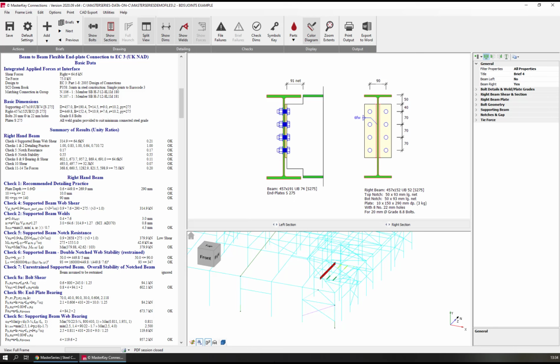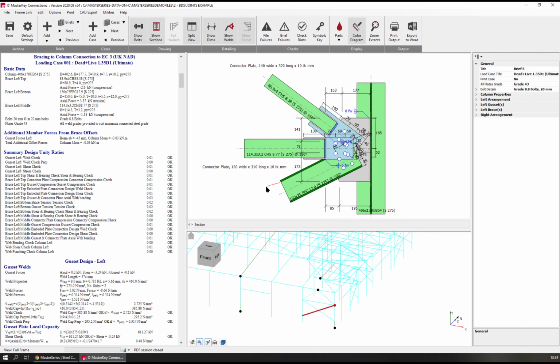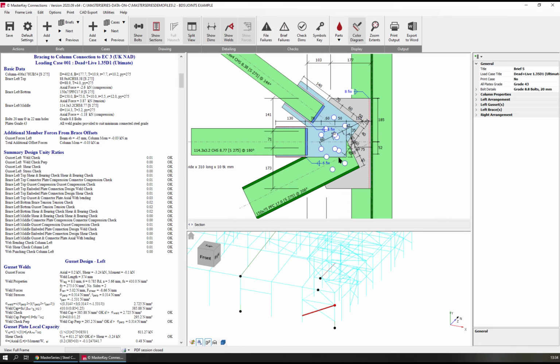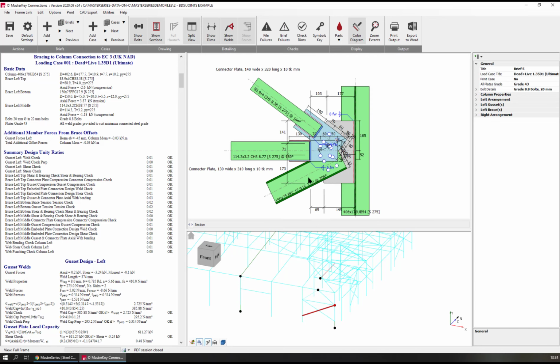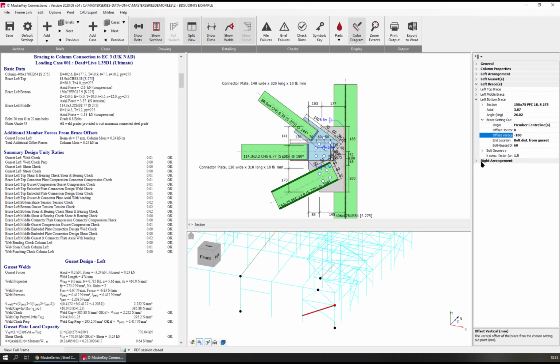Now we've got some more interesting items. We've got a bracing connection, which is coming in with PFCs and circular hollow sections. So obviously that's clashing at the minute and there's a bit of a log jam. So maybe we should spread this out a wee bit. So if we take this bottom and we bracing set out, and we're going to offset it by hopefully minus 100 is downwards. Yes, it is.